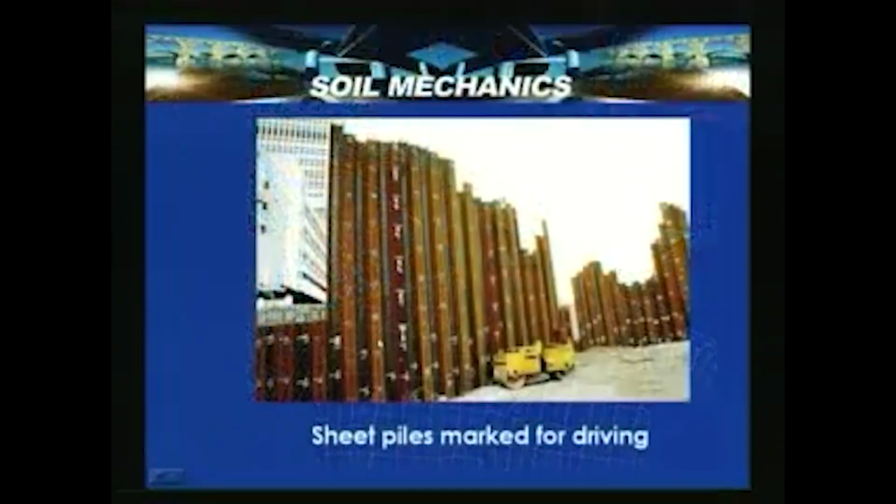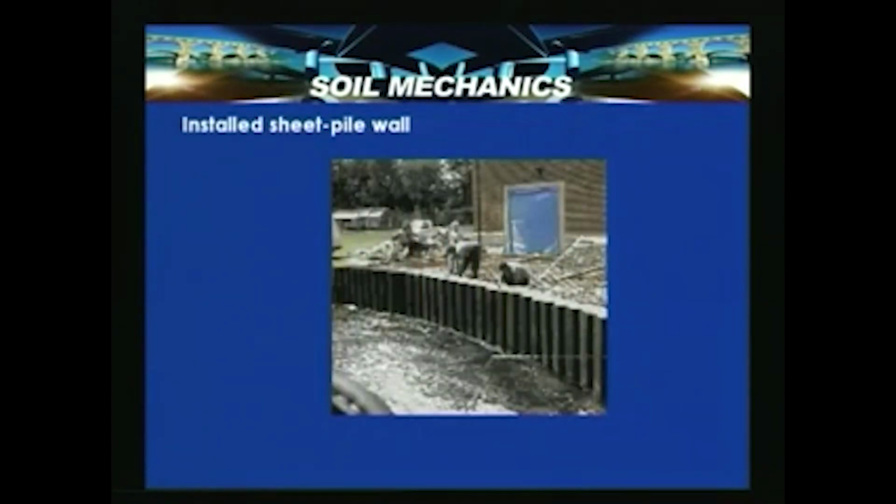So in this slide, a typical sheet pile wall is shown where these are marked for driving into the soil. Sometimes these are also used for protecting temporary excavations, like what you are seeing here, a high rise building, to prevent any collapse of the soil in front of these, particularly these sheet pile walls which are driven into the ground to retain the soil behind this particular section. This is an installed sheet pile wall.